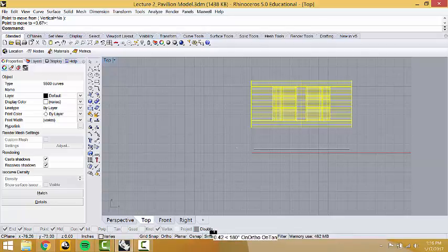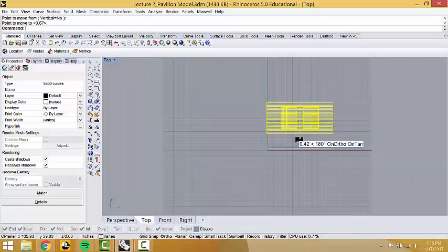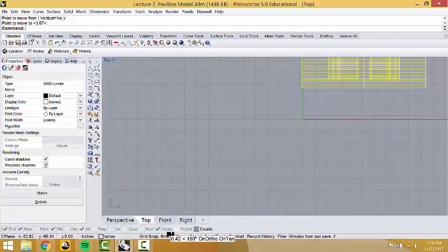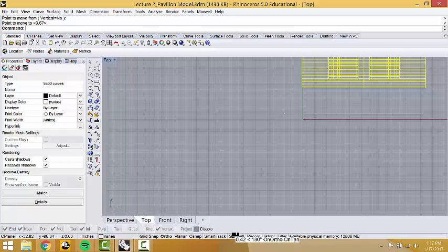I think when you just start Rhino, there is nothing turned on down in this pane. So ortho, you already know about. That keeps things going either perpendicular or parallel. Planar, I never mess with planar, but you can understand what that does. Gumball, if you're feeling like working with that. Smart track, I usually keep that on, and O-snap, I usually keep that on.